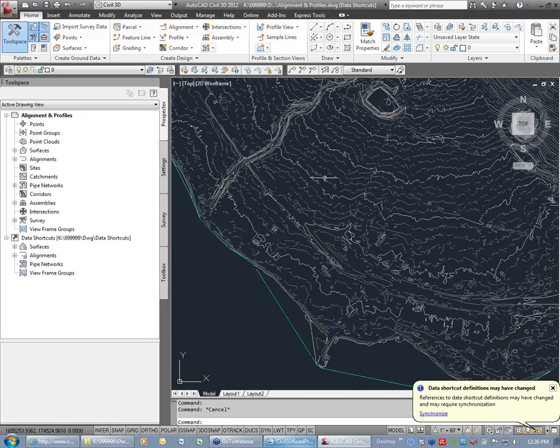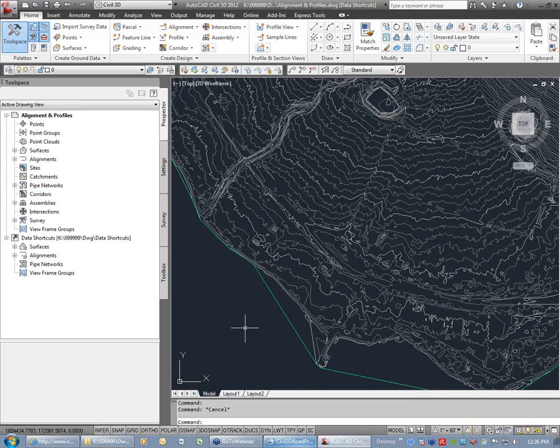Okay. After saving it, go back to the drawing. You'll notice this thing just popped up. This typically only pops up if you're the only one in the drawings. If someone else is in the drawing and makes a change, it doesn't always come up. Okay. So I'm going to pretend here that it didn't come up. I didn't see that happen. Okay. There is an icon down here at the bottom right that shows you that there is a data shortcut reference.